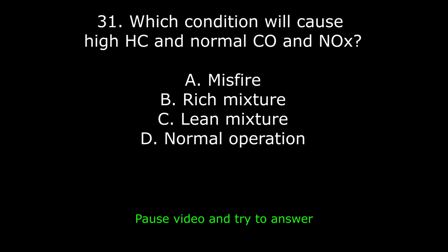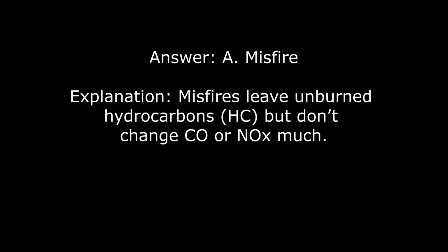31. Which condition will cause high HC and normal CO and NOx? A. Misfire, B. Rich mixture, C. Lean mixture, D. Normal operation. Answer: A. Misfire. Explanation: misfires leave unburned hydrocarbons, HC, but don't change CO or NOx much.